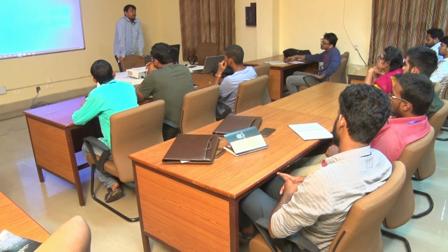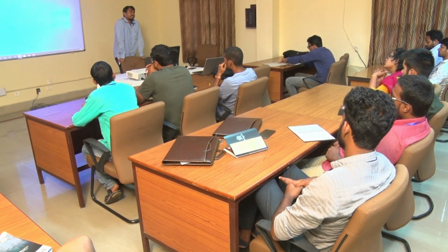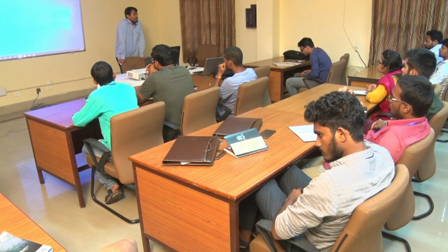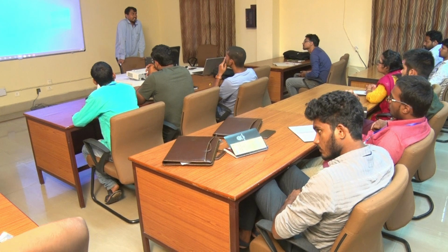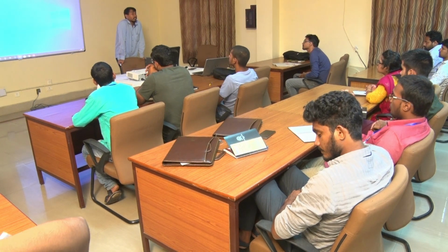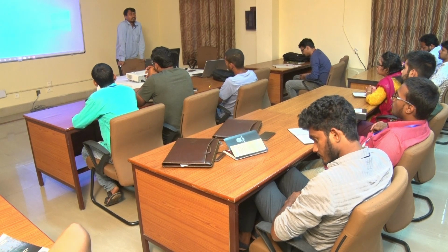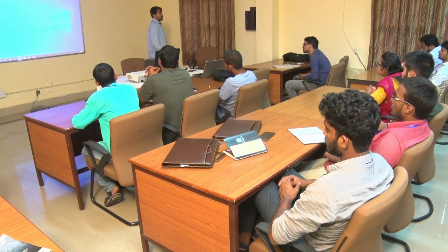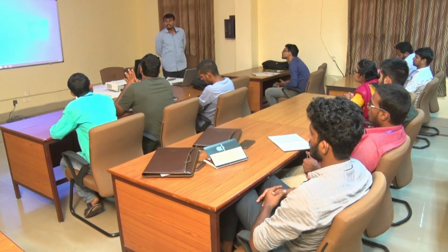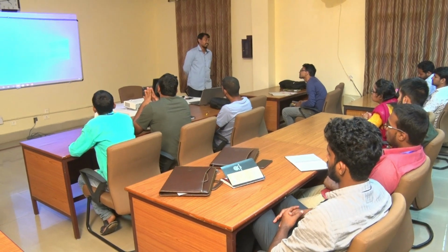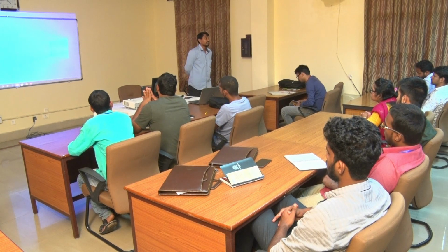So at that condition we will prepare the sample and test it in the triaxial laboratory. Similarly, we will also test the sample in direct shear to find out if there is any difference. Generally a difference is observed, but we take the triaxial test result as more accurate, and that will serve the purpose, the C and phi of that particular heterogeneous material.